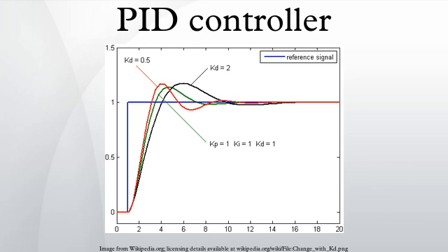Mathematical PID loop tuning induces an impulse in the system, and then uses the controlled system's frequency response to design the PID loop values. In loops with response times of several minutes, mathematical loop tuning is recommended, because trial and error can take days just to find a stable set of loop values. Optimal values are harder to find.